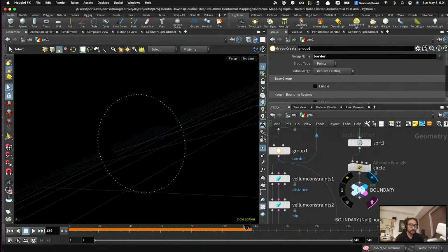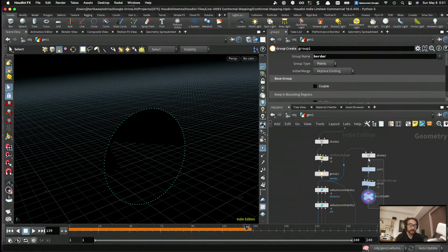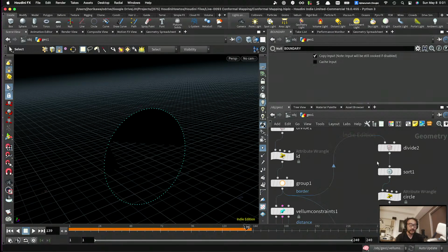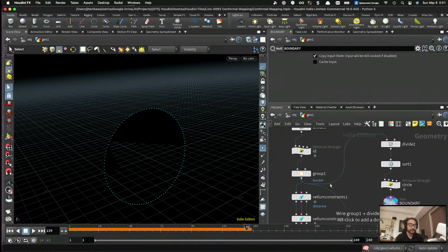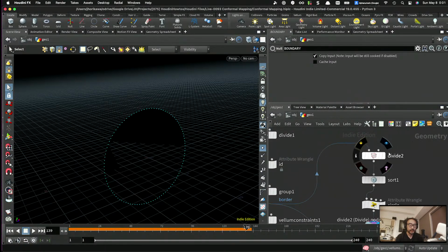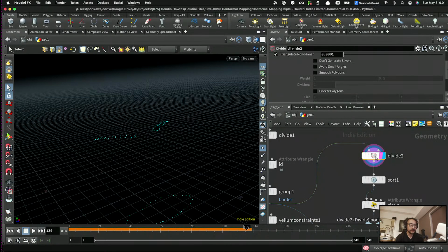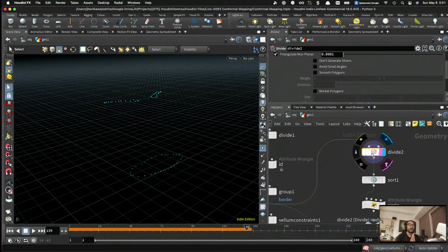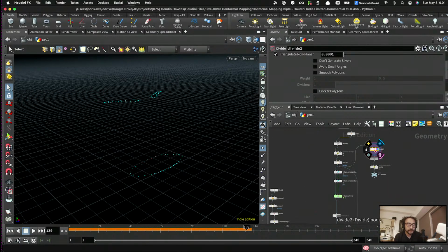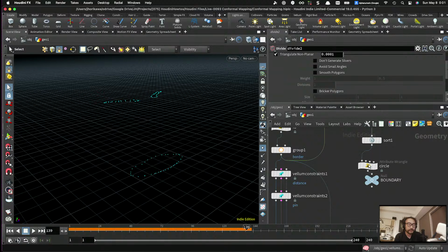Now this has a little bit of a problem because I am assuming there's only 1 hole, so I'm just creating a single circle, but instead we have 3 holes. So meaning you have 3 different border geometries out of this divide node. So that's one thing I need to be careful about, and do something about.